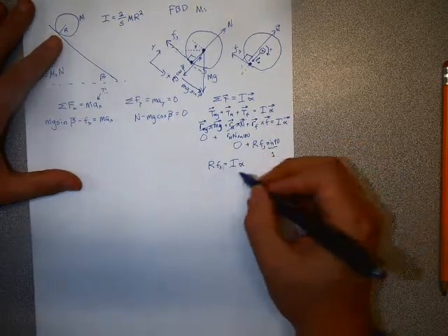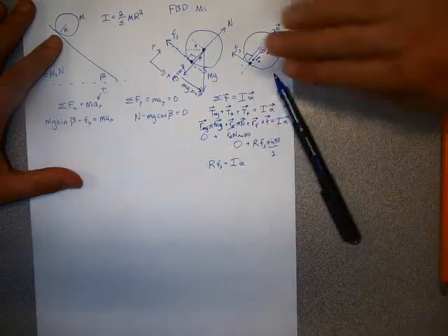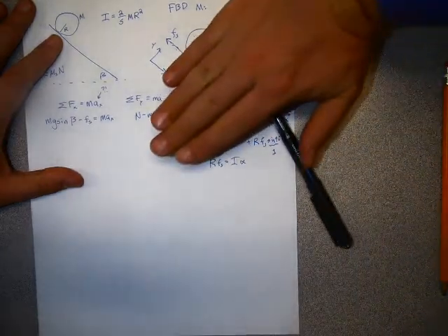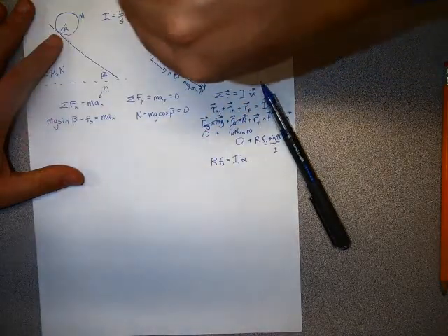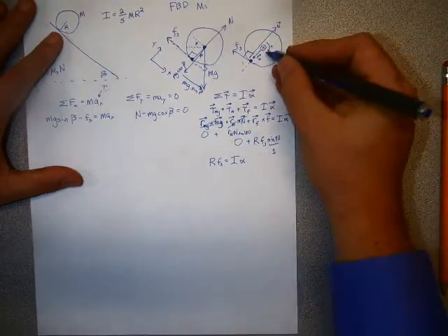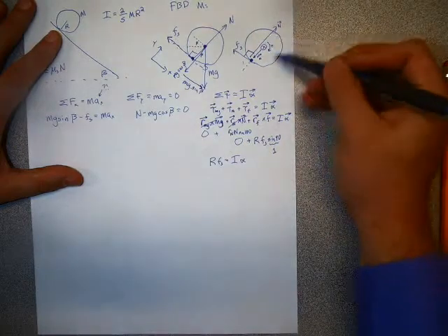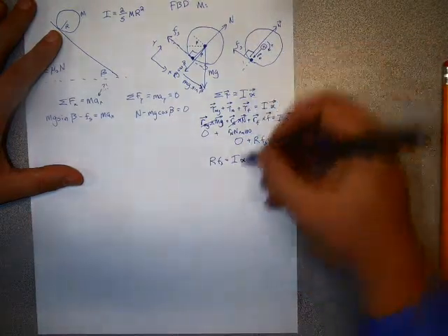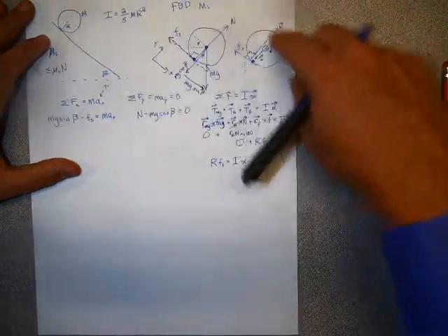Note, let's check the direction of this really quickly. If we do the right-hand rule, our whole arm in the direction of R_n, we roll our wrist until our fingers can flap in the direction of F, then my thumb is into the board, and so this is a positive direction for us, clockwise from this view torque. So alpha is going to be in the positive direction, which is what we'd expect. We'd expect for the ball to roll like this.